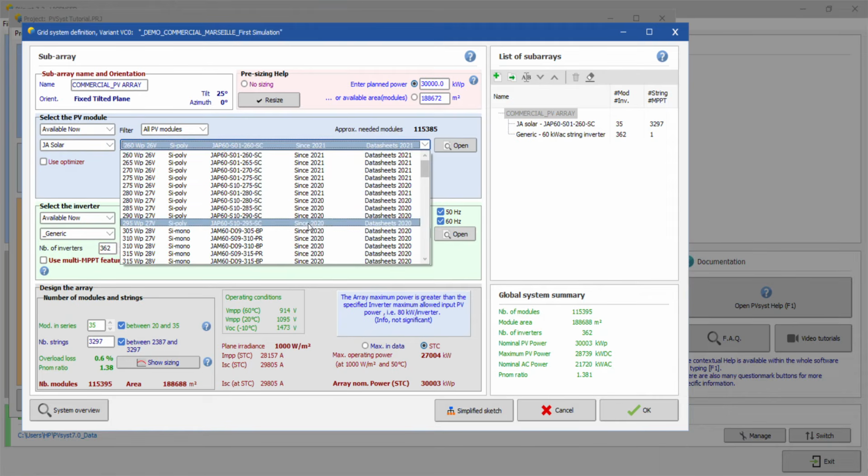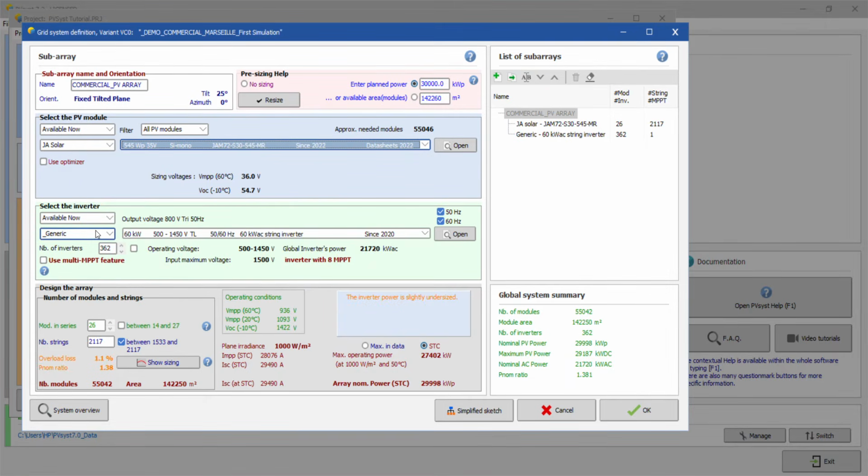Okay, and then the top 450 or 550 Wp modules are used for this specific system. I will select 545 over there. It depends on your case whether you have a different module. Sometimes the module is not available in the system, then you have to assign a PAN file and import a PAN file over there, and then select your module. As I already mentioned in previous videos, how to import a PAN file and OND file of inverters.